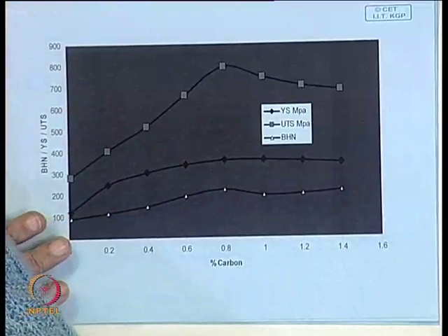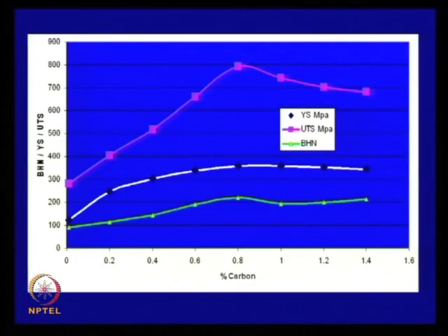I think the next diagram here typically shows, whatever I talked about, you look at this with carbon content. I took this data from handbooks for steel which are cooled at a very slow rate, annealed steel, and this axis gives Brinell hardness, shown by this. So, look at this part, the hypoeutectoid steel, it is very strongly dependent, but thereafter the change is not much.